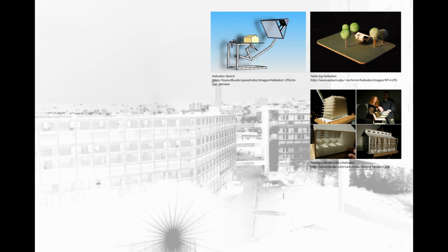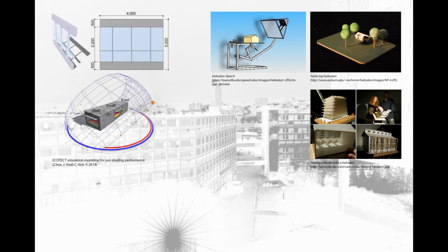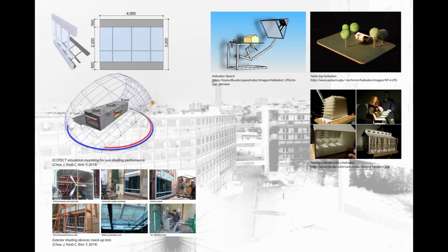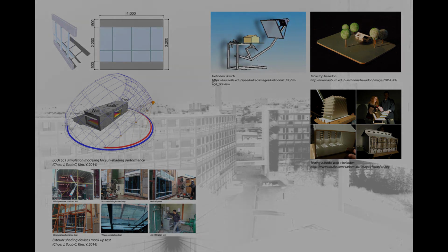For specific projects or briefs, it is best to carry out tests and simulations, such as a simple model in Heliodon, to more complicated calculations and simulations such as Ecotect. This is where tests and tweaks can be carried out to your building, where it will enhance its efficiency and energy consumption as best as possible to face the future changing climate.